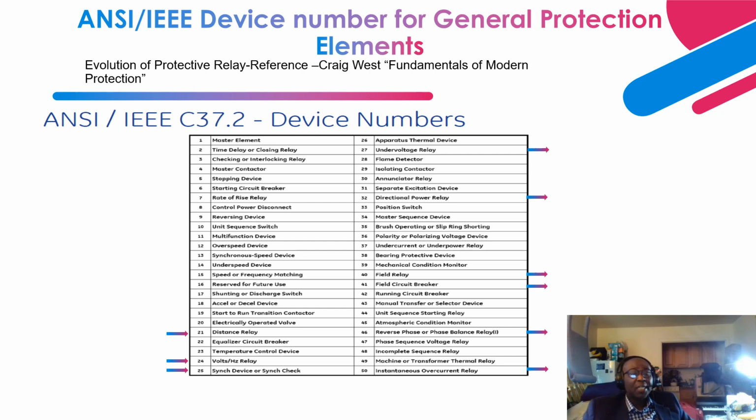So let's say a negative sequence unbalance of 5%, 6%, 10%, for a certain period. So I squared T, and it also provides a K, and the K number is a multiplier that is provided by the manufacturer.